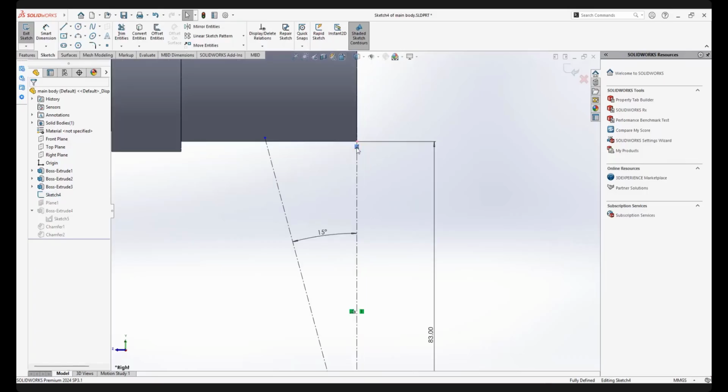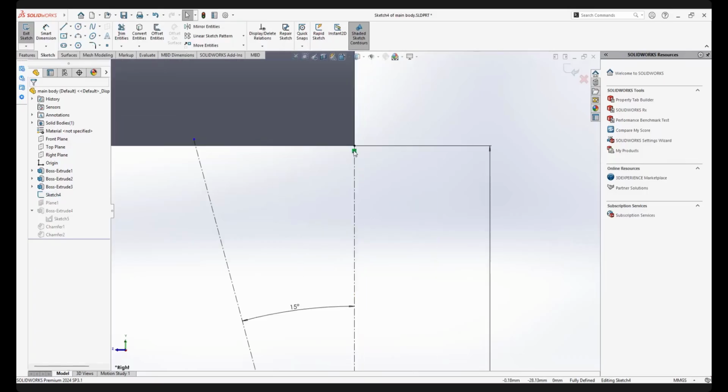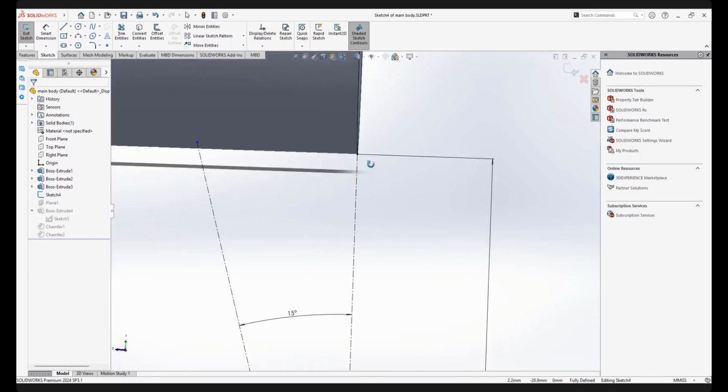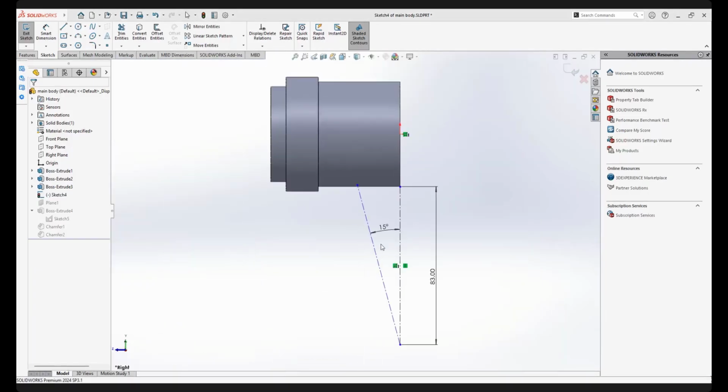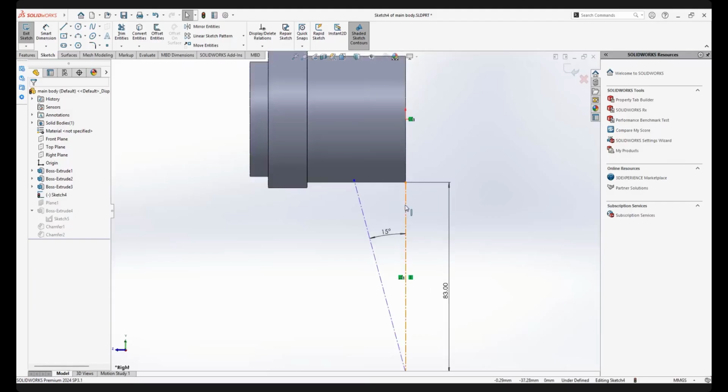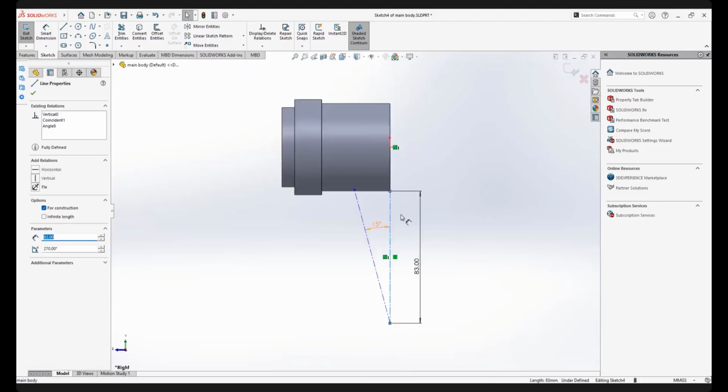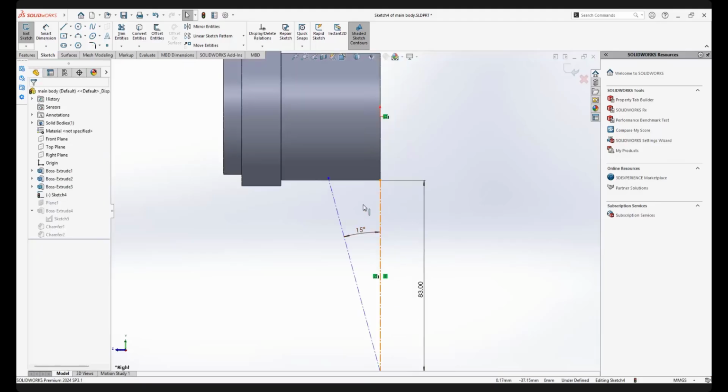So here, this one, I already have a coincident relation. It coincides with this point, the quadrant at this edge. Okay, the quadrant of that circle, all right? So I select the relation that becomes blue color. So I delete it, there's no relation there. Let me go back to the perpendicular view again. So this one becomes blue color because we miss the coordinate position. So it means that I can shift this thing. All right, I will shift.